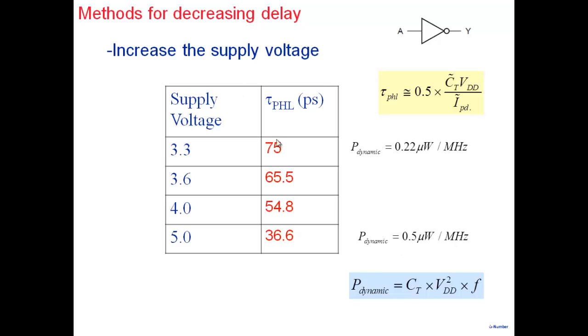If you increase the supply voltage, well, you're decreasing the delay, but the power dissipation, as you can see here, if you've made the delay half, the power dissipation has also doubled here. So that's one of the prices that you pay.